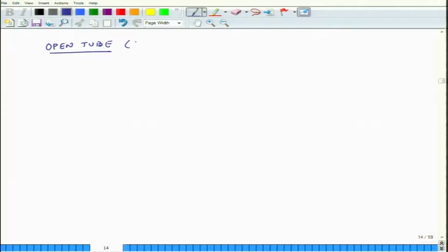and this open tube has to be short. So, this is how the scheme looks like. This is my long tube, and if this is the cross sectional area, and let us say the cross sectional area is S, then I can attach an open tube on the side of it, and this open tube, which is not too long, actually it is a short tube, can also act as a resonator and it can kill a lot of noise associated with a particular frequency.